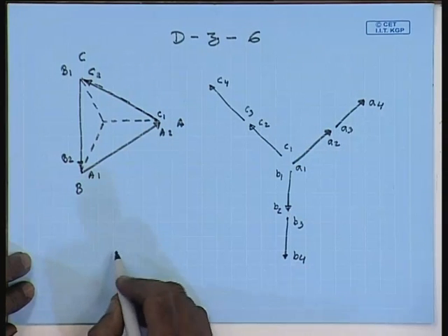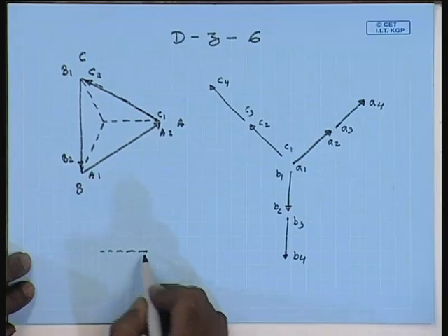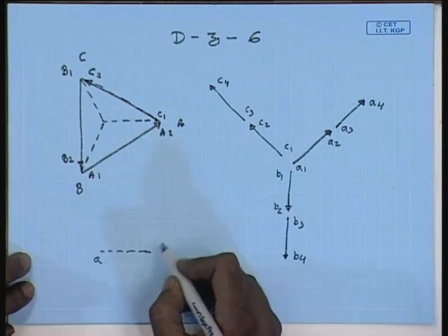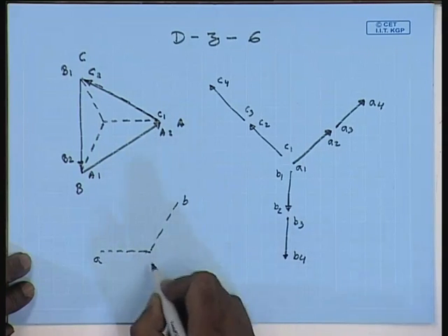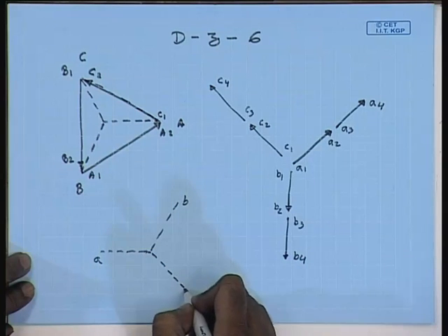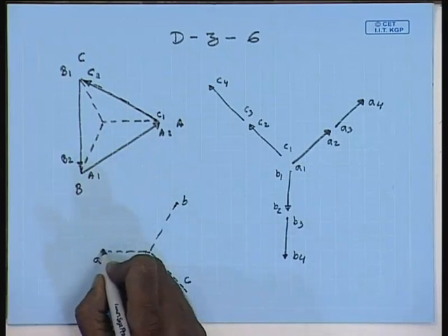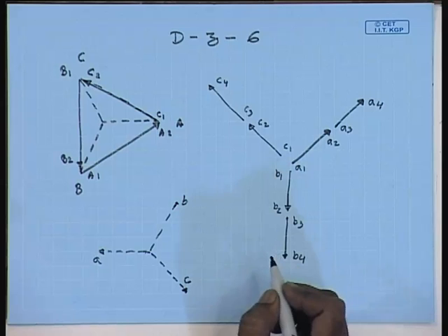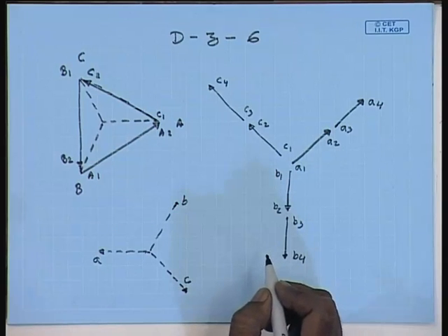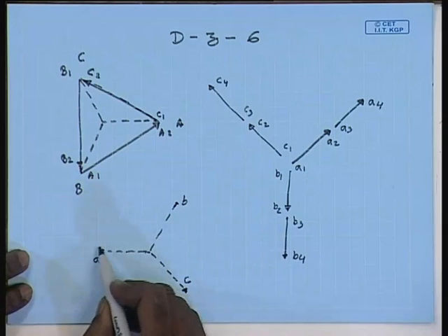So, the line to neutral voltage phasor on the low voltage side will be, this will be A, this will be B, and this will be C. So, the last leg should be formed with a voltage phasor of A, and it should point towards this.